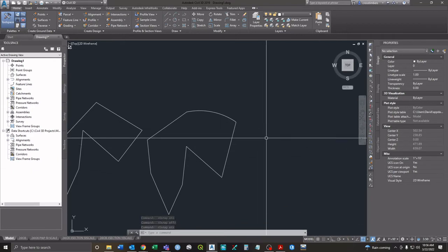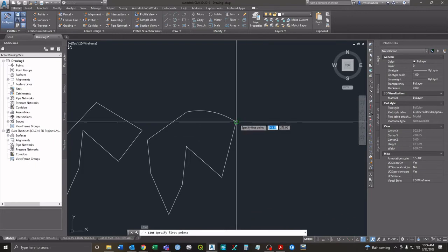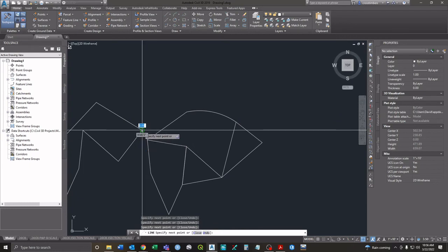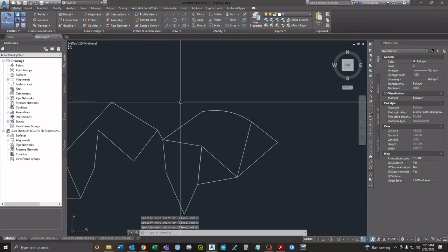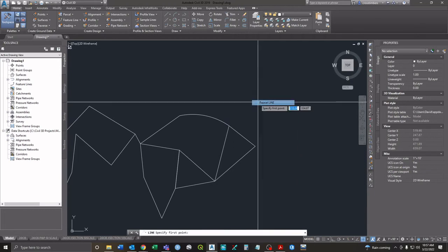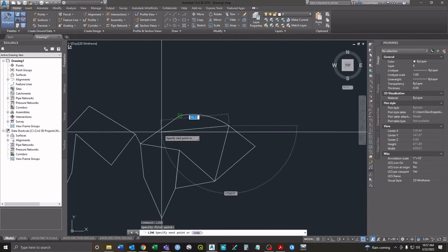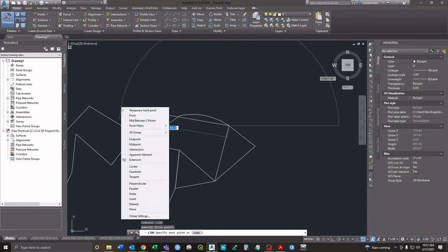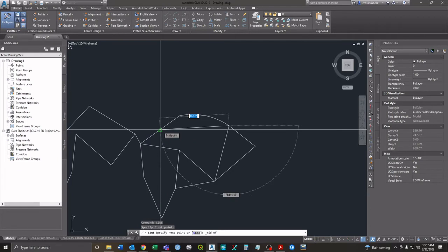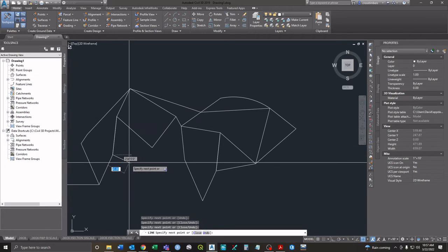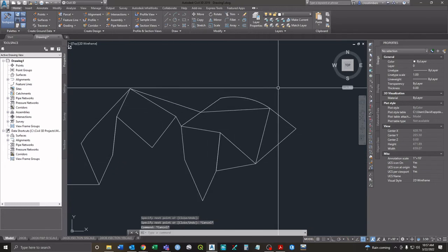Okay, but so if I just leave it on, then I can easily go here, here, here, here, you know, so if you're doing it a bunch in a row, that's really easy, because the shift right click thing obviously is very slow. But say I want a line, I want to start at this endpoint, but I want to go to this midpoint. Well, I only need one midpoint every once in a while, so I'll shift right click, go to the midpoint, okay, now I can keep doing my thing. You see what I mean? Yeah. So that's a personal preference.